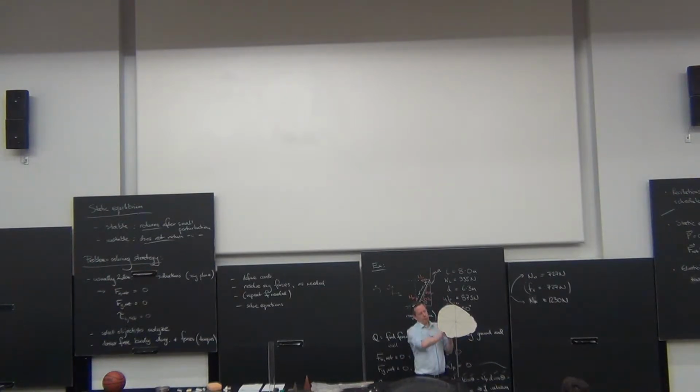Looking at a vertical line passing downwards through the hanging point, everything on this side of that line, with gravity acting down, tends to turn the object this way. Conversely, everything on the other side tends to turn it that way. So once it comes to rest, there's no net torque, and this vertical line tells us that the center of gravity of this object is somewhere along that line.